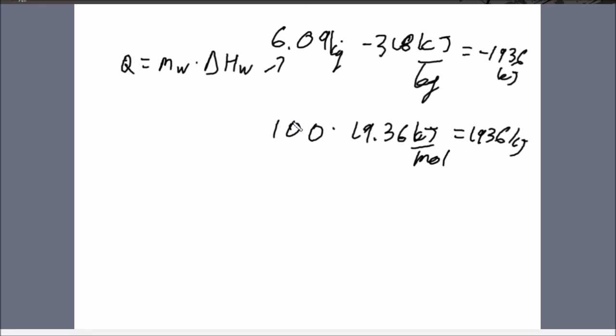He might also throw in the heat exchange membrane getting dirty. Maybe he'll give you a specific number, like the efficiency of the exchange is only 75% now. That special symbol that looks like an n is the Greek letter eta. So then you do the inverse of 0.75, which is 1.333.